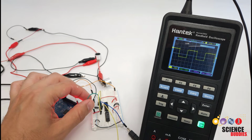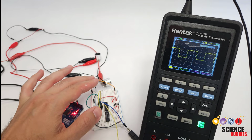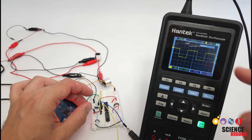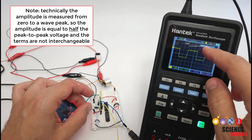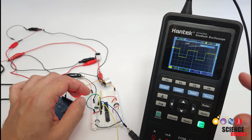So I realize all that was probably a lot to follow, so I'm just going to demonstrate it. I have disconnected the transmitters and just hooked up my oscilloscope to measure the voltage output from the H-bridge. And I have the auto measurement set to measure the peak-to-peak voltage or amplitude of this wave, and right now that is right around 12 to 13 volts.